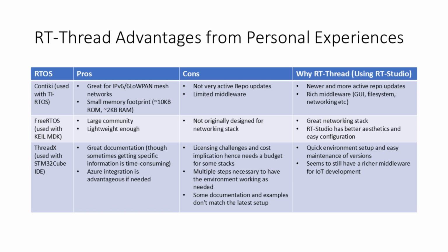They were required to be able to have a system that can transmit data at most every 3 seconds, and when transmission fails for more than 3 minutes, it must alert the transport authority. The way they had developed the application with Keil and using FreeRTOS, it was not possible to actually extend their development.